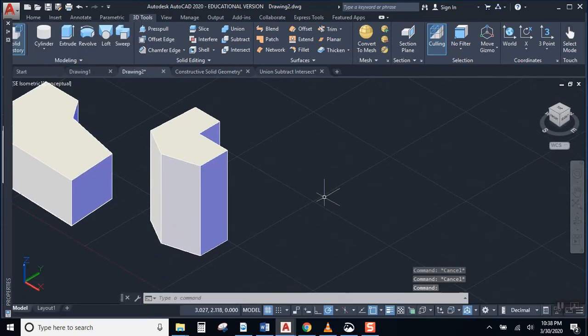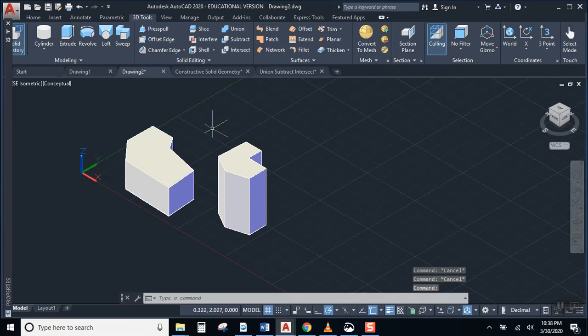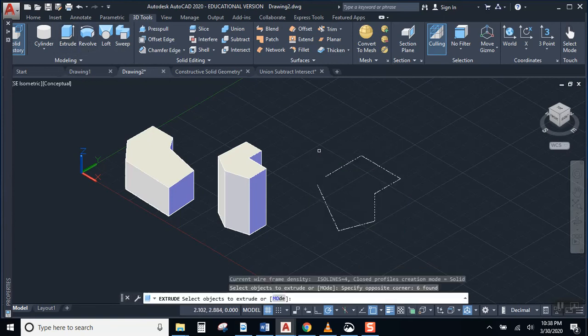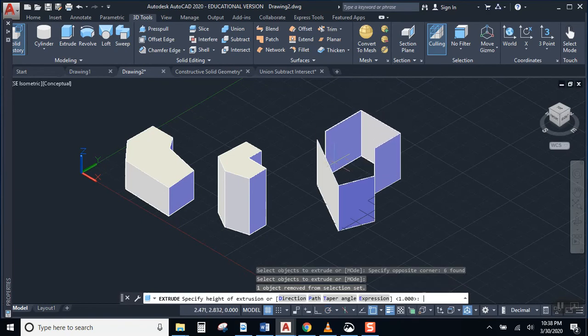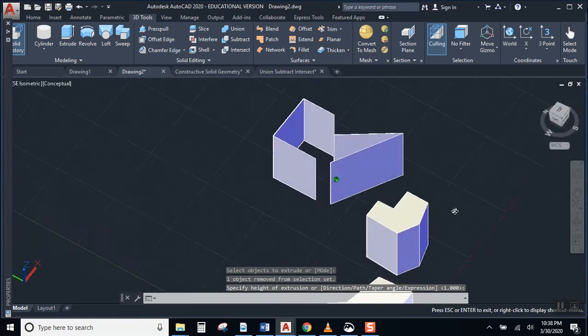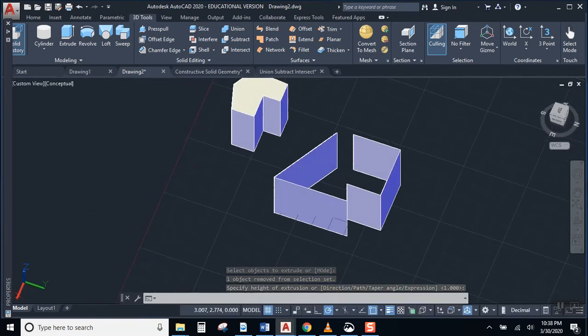Very good. What we don't want to do is draw lines and then leave a gap. Because if we draw lines and leave a gap and go to extrude, we're not going to get the results we were hoping for. Right? That looks like there's some solidness to it, but you know what this is? This is really a bunch of surfaces, a bunch of regions.